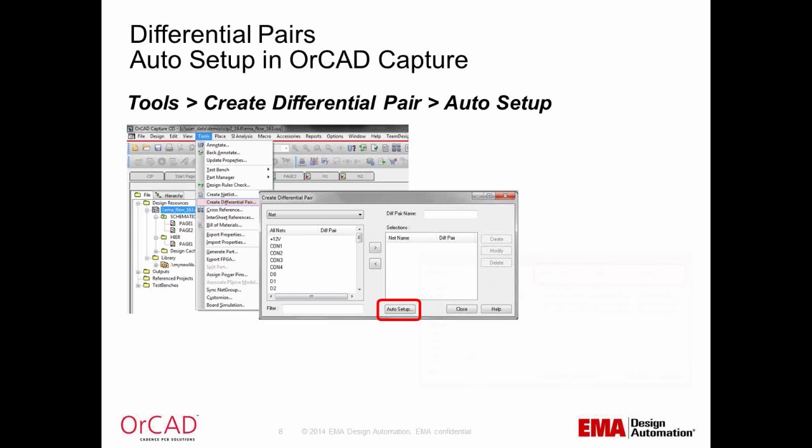So you'll first select your design in the Project Manager, and then select Tools, Create Netlist from the top menu. In the resultant form, you will click on the Create PCB Editor Netlist and Create or Update PCB Editor Board checkboxes. Then you will fill in the input board file name if you have one. An input board file might be a template board file that contains a board outline, layer stack-up, and maybe even some constraints. Next, you will fill in the output board file name as desired.